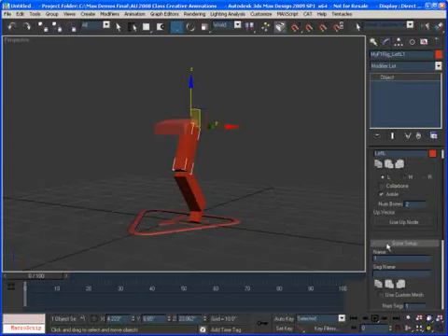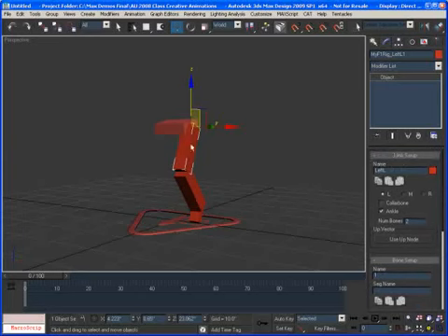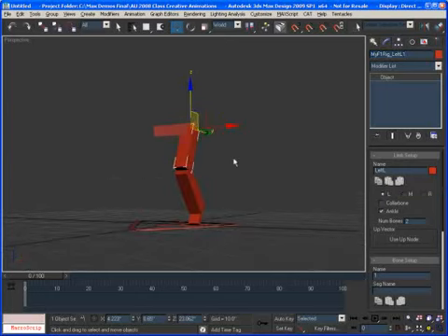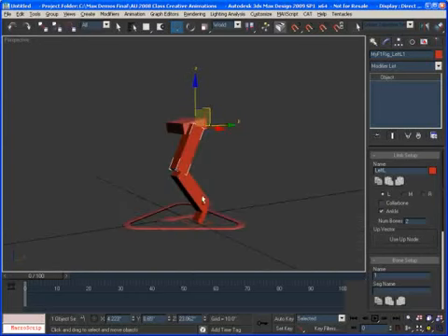But all of this renaming bone setup, the name of this specific bone is added to the name of the group, which is a limb here called left L. All of this will be added together with the name of the rig and will be the name of that bone. So you see that the name here for the bone is that compilation of all these naming sections. You see that this leg here has been set up to be left. We could also set it to middle or right. That's going to be useful when we do copy and paste operation, and also when we do automatic walk cycle with CAT motion. So this is going to be important. Right now we're using the left leg. That's kind of cool. And we've got the chain set up.